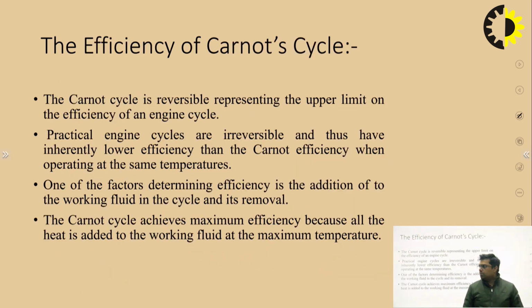If we talk about the efficiency of the Carnot heat engine cycle, it is called a reversible cycle, and its efficiency will be maximum compared to any heat engine cycle. Practical heat engine cycles are irreversible and have inherently lower efficiency than the Carnot efficiency when operating at the same temperature.